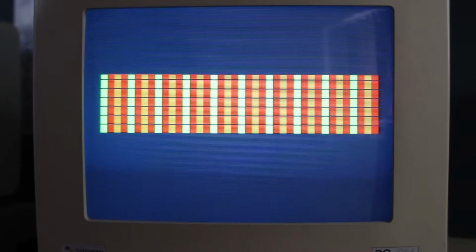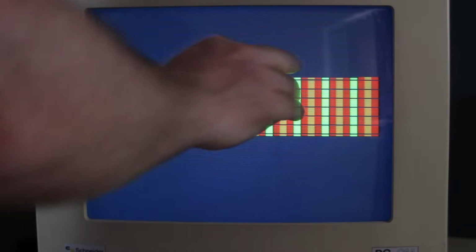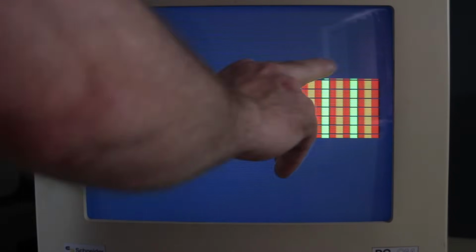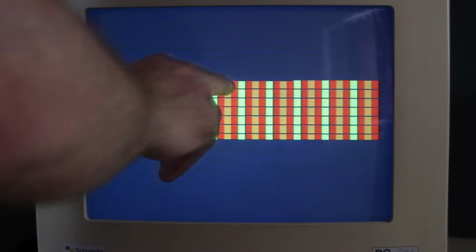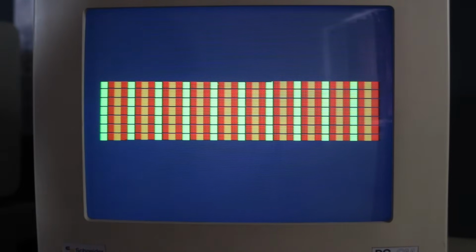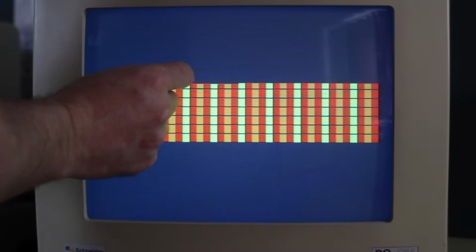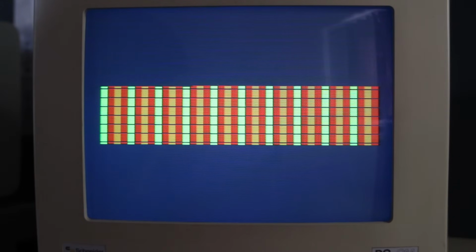Well, I also realized that in order to check for glitches in this graphics chip, I don't actually need to stop the movement altogether and get very precise control over where things are happening. I can actually just let it scan through by just drifting naturally the way it already is, and that'll check all of the different locations in the frame. So basically this is visual mode in my code, and instead of changing the background color very briefly up here and then down here, I'm using the time to change one of the registers in the CRT controller chip, the graphics chip that we're trying to study.